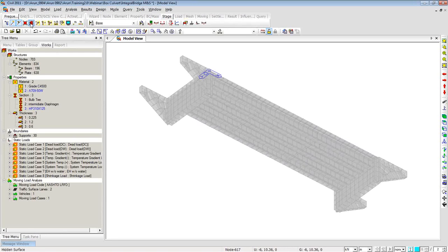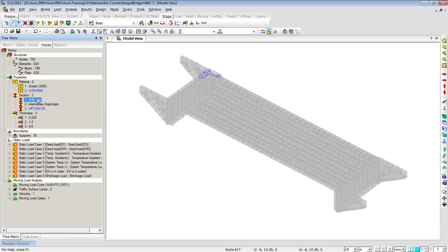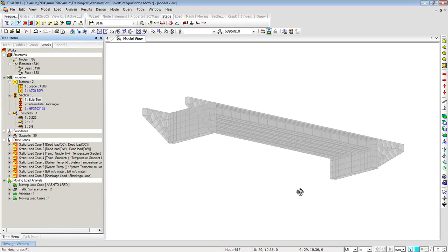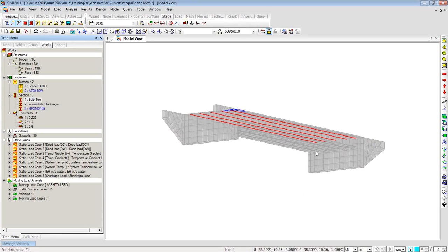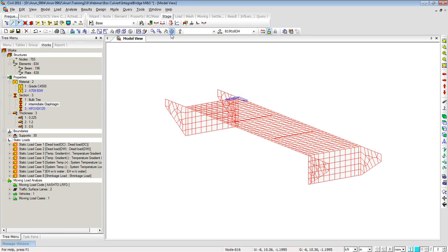I can choose to just double click on girders so you can see the girders are right there. Basically due to the same color they are difficult to see. So the geometry is ready. Now I'll quickly create the piles underneath the structure. So let me switch to a wireframe geometry and unselect everything,